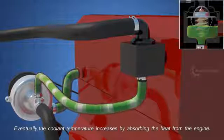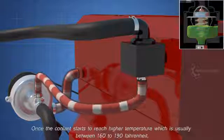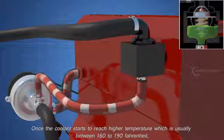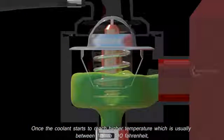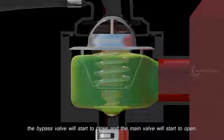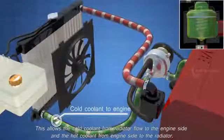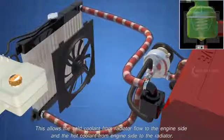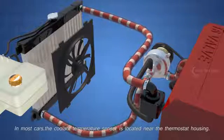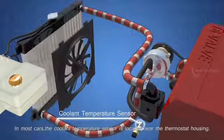Eventually, the coolant temperature increases by absorbing the heat from the engine. Once the coolant starts to reach a higher temperature, which is usually between 160 to 190 Fahrenheit, the bypass valve will start to close, and the main valve will start to open. This allows the cold coolant from the radiator to flow to the engine side, and the hot coolant from the engine side to flow to the radiator. In most cars, the coolant temperature sensor is located near the thermostat housing.